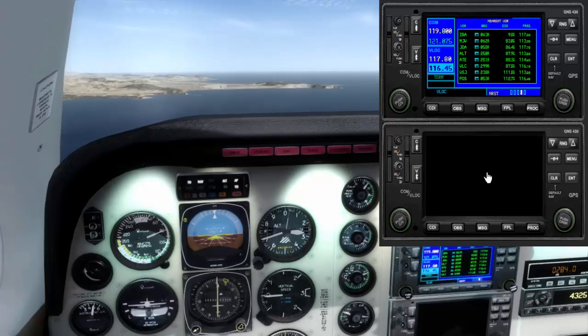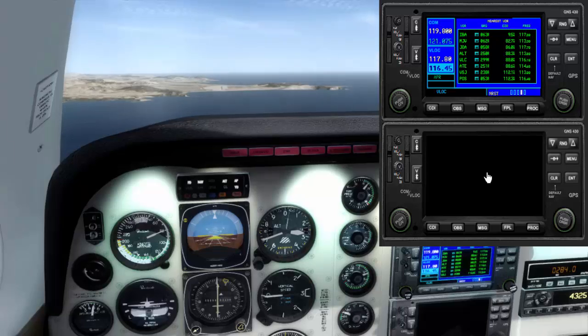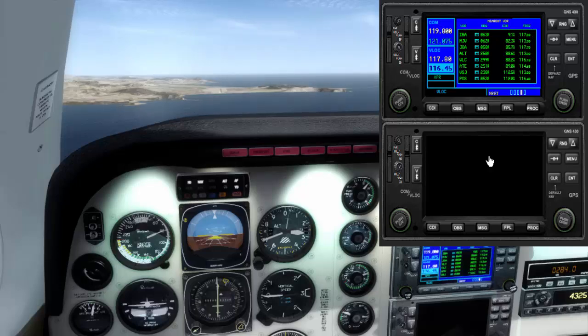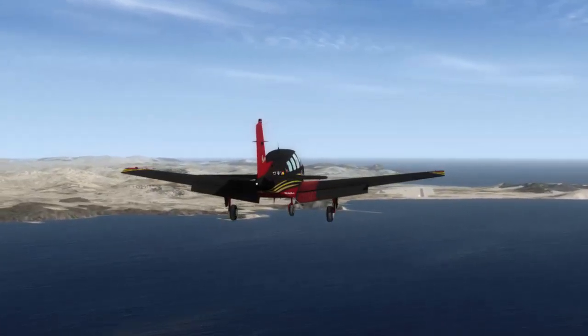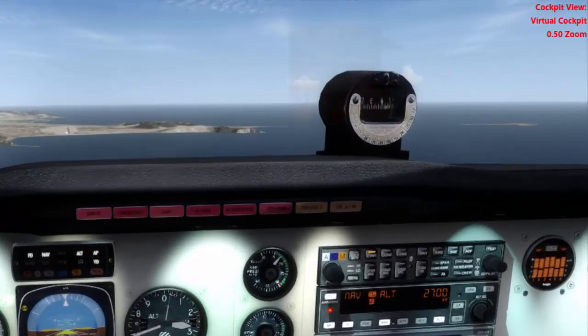9 nautical miles. So take a look all the time at the nearest page, because when we reach 8 nautical miles from the IBIZA VOR, India Bravo Alpha being the identification of this VOR, at that point we will say that we have reached the final approach fix, and that is the moment in which we have to descend our aircraft. And as you may see, we are following real procedures, the real procedures a real pilot will follow to approach Ibiza, and we have the runway in front of us, so we are doing the right thing.